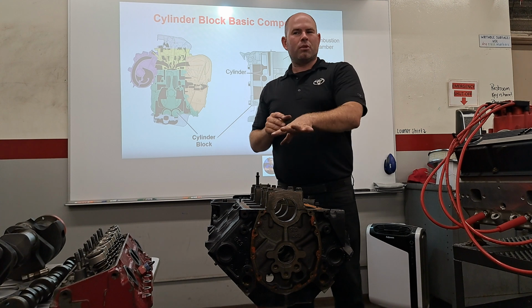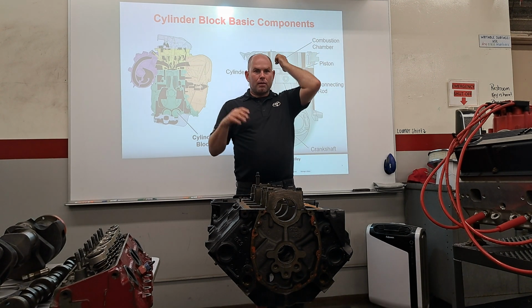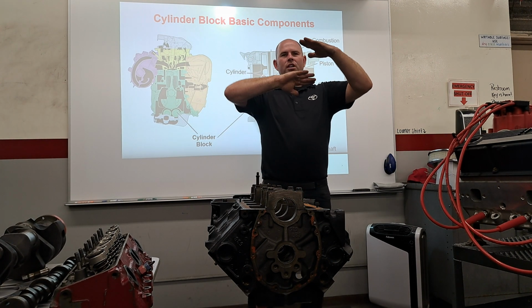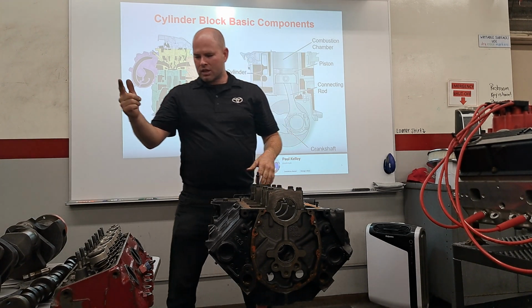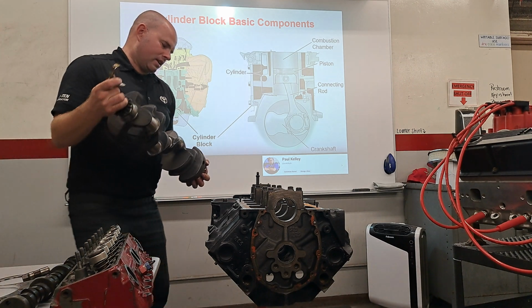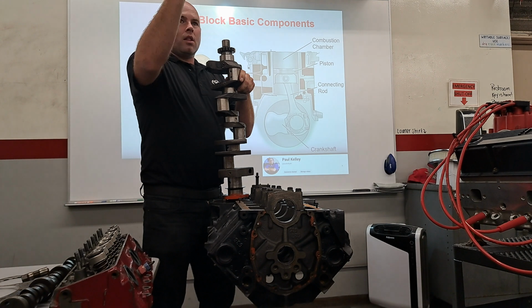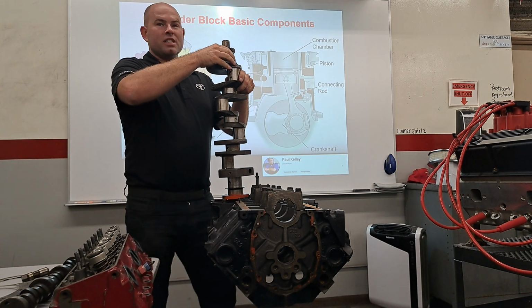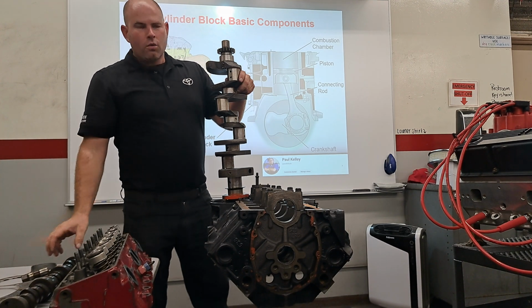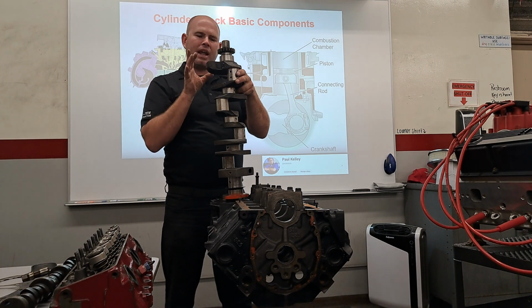Okay, but I forgot to put oil in there because I'm all crazy, and all of a sudden there's a lot of friction there, right? The crankshaft is spinning because I had that bearing, right? So if you were to take this crankshaft and visualize it, which I can probably get away with this. The main bearing's right here. It has to spin on that main bearing. Cool? But it really needs the oil. If I forget to put oil in there, this doesn't build oil pressure. Now this contacts the main bearing and starts to wear out the main bearing, right?